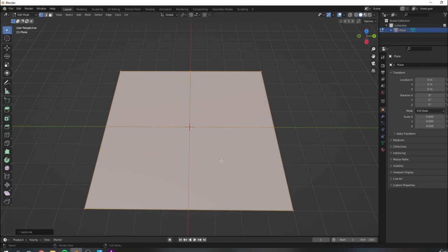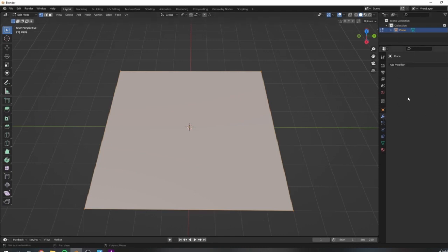And we discussed this earlier in the course. However, we are not going to be doing it via regular mesh modeling. We are going to be using a subdivision surface modifier because this speeds up the process just a little bit. So in the properties panel on the right here, click on this wrench icon to bring up the modifiers panel. So modifiers are automatic operations that affect an object's geometry in a non-destructive way. With modifiers, you can perform many effects automatically that would otherwise be too tedious to do manually, and also it will not affect the base geometry of your object.